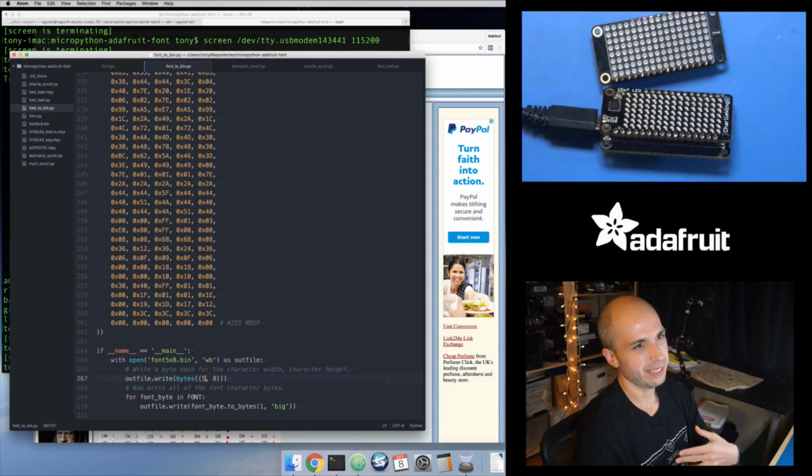That's nice in that I'm maybe making a font file format of sorts for this, so that I don't have to hard code into my font renderer that it only works with 5x8 pixel fonts. This way I could have maybe 7 byte long fonts, 7 characters wide or 8 characters wide. I could change this, but I'd have to make sure that I change all this data to match that. The first byte is the width in pixels of each character. The second byte is the height in pixels of each character, so that's 8 pixels.